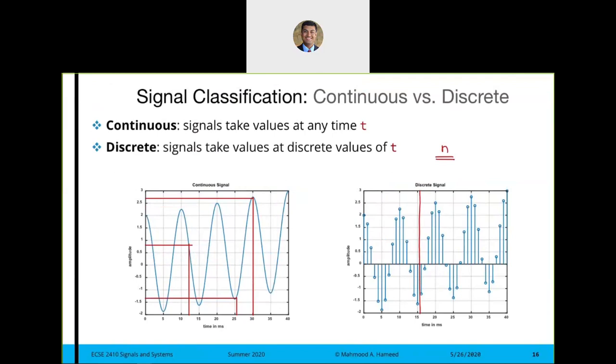You would pick out some values and say, okay, this is enough to represent everything there is to know about my height. In the same way, you can sample a signal to convey all the information that is necessary. Instead of sending, processing, and storing all the information about a signal, you do that only for limited, discrete time values. More about sampling later on in the course.